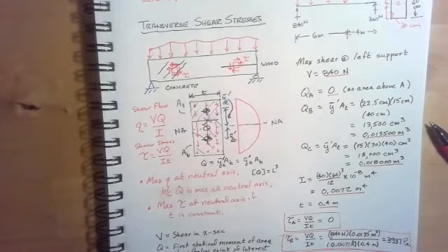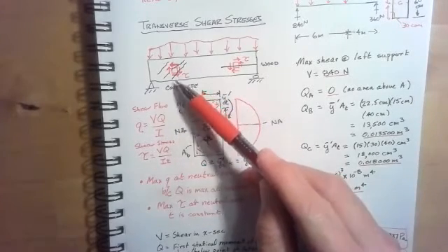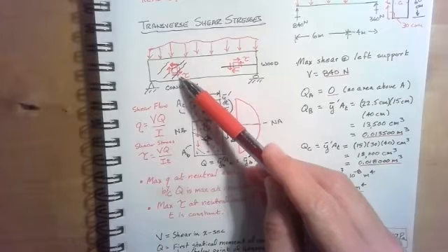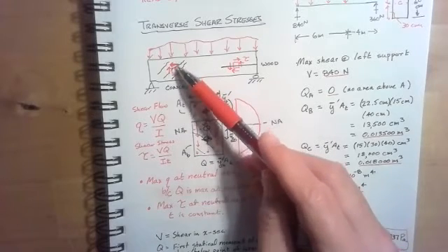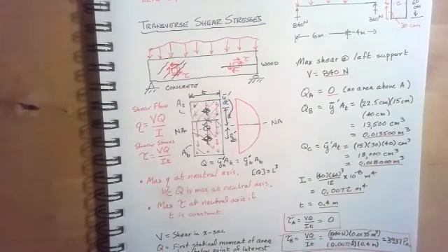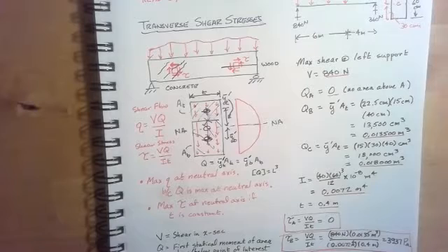However, for concrete, you might see shear cracking that happens at more of a 45-degree angle orientation. And you can imagine that these two shear stresses pull downward, and these two shear stresses pull upward. And you end up with concrete in tension, and concrete is extremely weak in tension. And you can have shear cracks that would come at a 45-degree angle, and without adequate ties or stirrups in a concrete beam, shear cracking could cause a concrete beam to just drop out between the supports.